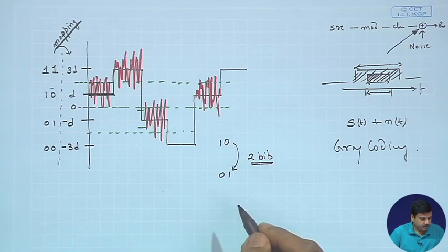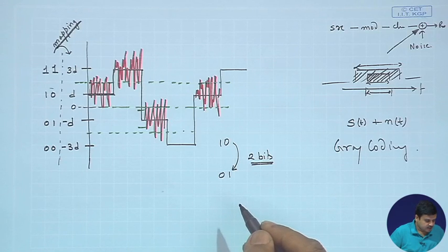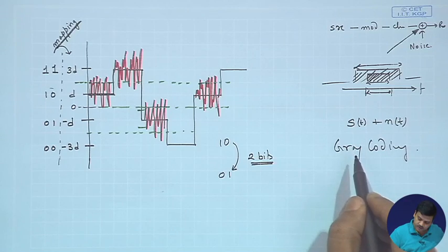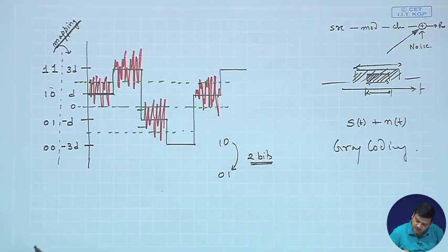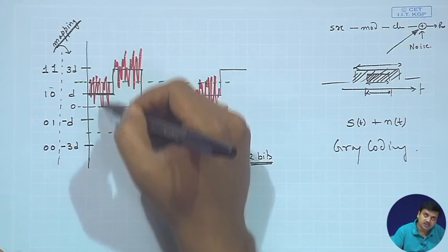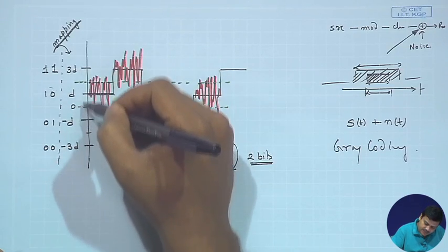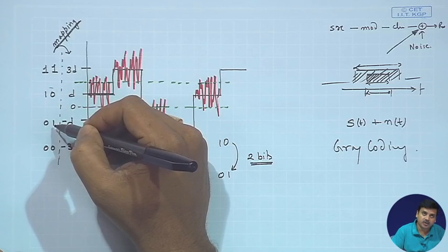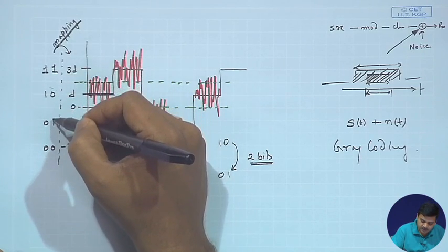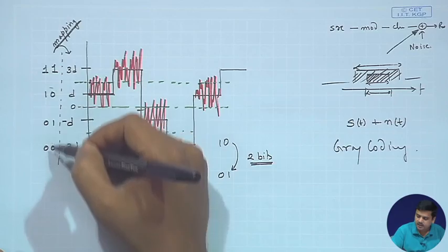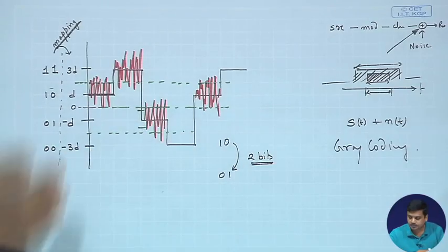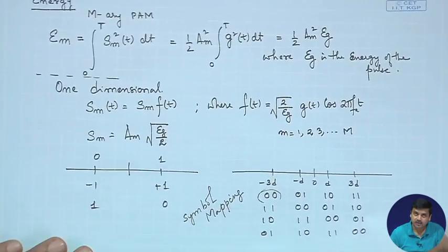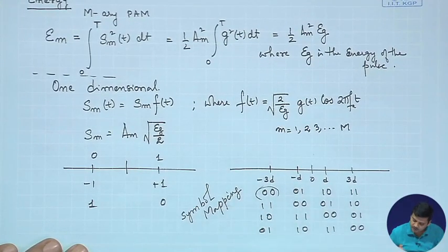The idea behind Gray coding is that you would try to map the particular bits to symbols in such a way that when these changes occur, or these neighboring amplitude levels are mapped by bit sequence in a way that the neighboring bit sequences differ by at most 1 bit. So, what I mean is, if we look at these particular possible options.